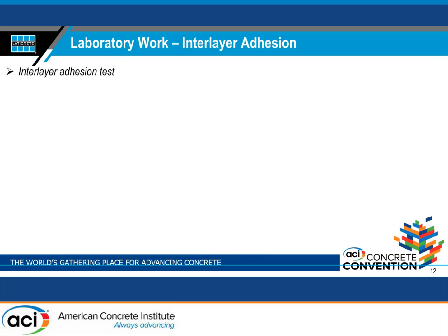It has been reported that one of the challenges in this technology is the lack of bonding adhesion between the printed layers. So we evaluate the adhesion by testing cold joint specimens and non-cold joint specimens.